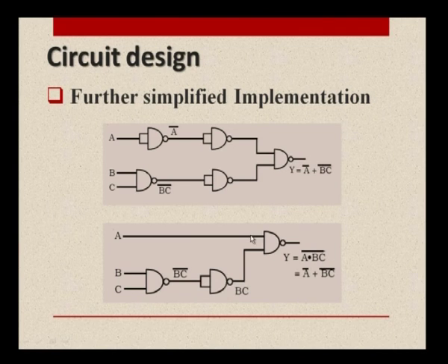It is A and this BC, these two are given as input, and this NAND operation is performed on it. When we look at this expression, it is not similar to the given expression, but when we apply De Morgan's theorem on this, with an AND considered between A and BC, we will be able to split the expression in this manner. So, finally, we require only 3 NAND gates. So, 2 gates are minimized. We get an advantage of it.